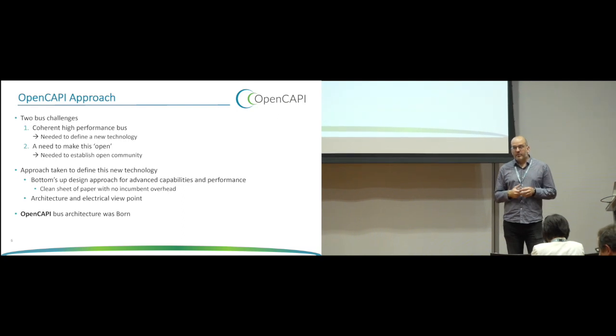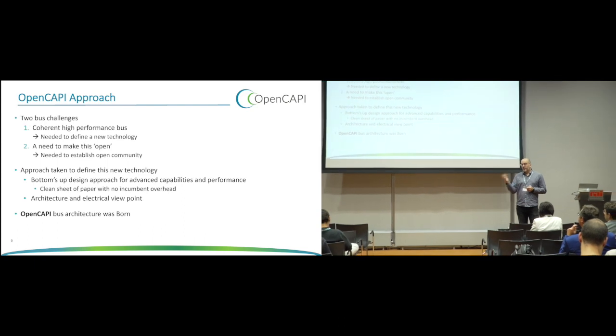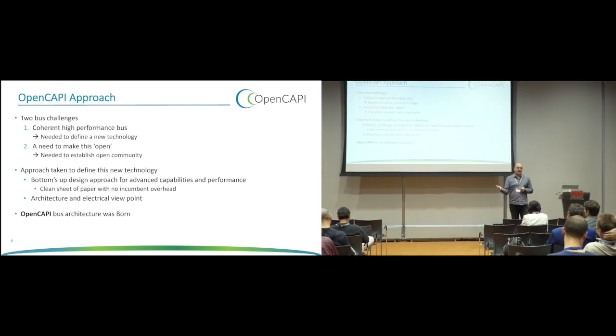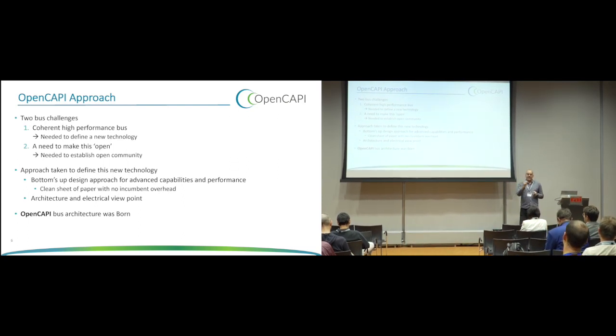Now that said, let's talk a little bit about what's not in OpenCAPI. Part of the reason PCIe has higher latency is it has very strict packets. The packets can go through PCI switches, and everything's self-contained within one CRC code. OpenCAPI, based around our experience with CAPI and the DMI memory interface, has a very naked interface. It's very tightly coupled to the processor, which in some senses means it doesn't encapsulate things as well as PCIe or Gen-Z does.